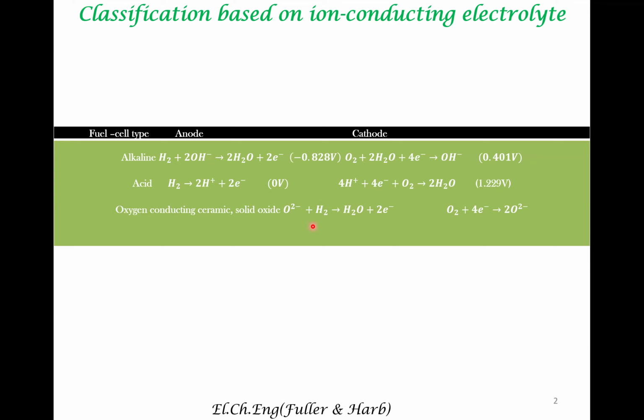one of the reasons why this configuration, the so-called solid oxide fuel cell, is an important approach to fuel cells is because the kinetics of oxygen reduction becomes simplified at higher temperature. If you want to increase kinetics, one way of doing that is via having high temperatures.